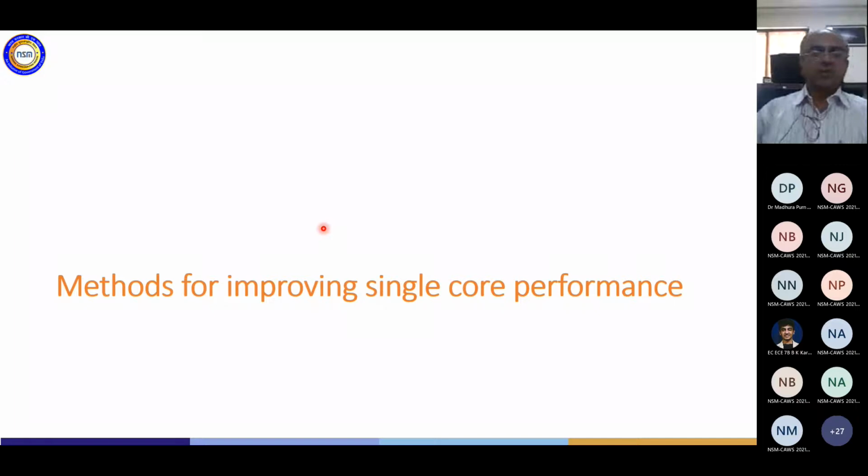So this was the background, how things work, the basic execution. We saw how a higher level language program gets translated into machine language, and we also saw that there are two types of architecture when you look at the instruction set, complex and reduced, or you can say complex and simple. In both of these, either the hardware has to do large work, or the software has to do large amount of work. Software has to do large work in RISC and hardware has to do large work in CISC. And that's where VLIW tries to strike a balance.